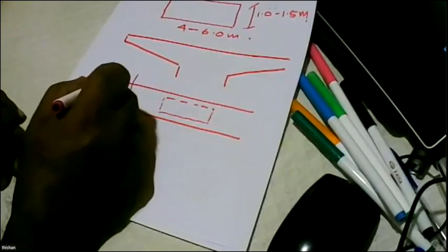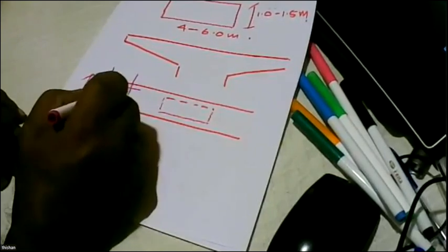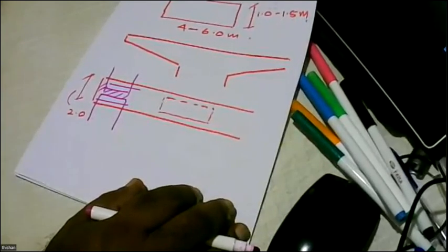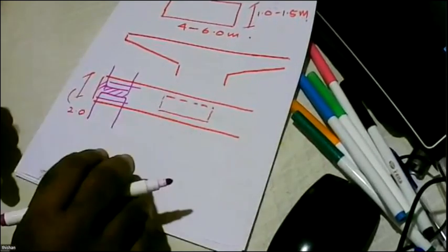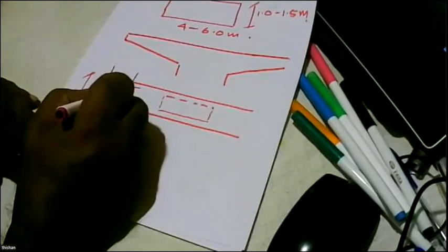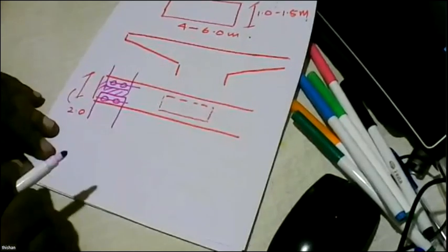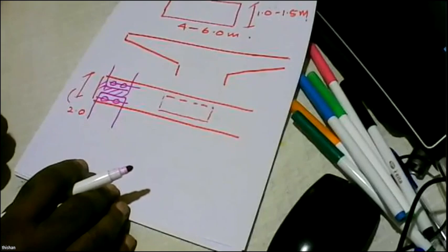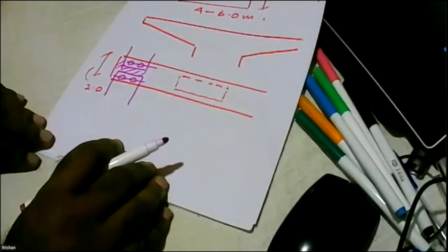And then you have to create a diaphragm connecting them. Depending on the type of connection, you might have to do something to ensure that the bearings can be properly placed, and also this continuity is taken into account. So which means you need space. So if we like to have a computer model, what are the options available for you? So let's see what are the options available.